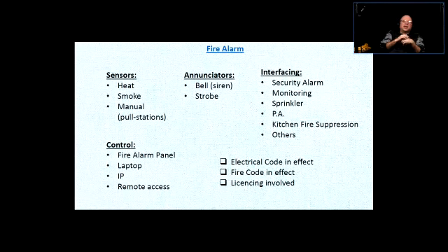So that's why in that case you would have to install something that's called a dry sprinkler system, so that there's no water, but in case there's a trigger, then the triggering of that specific sprinkler head would trigger the water being released from the main panel, right? So that's a different distribution between dry and wet sprinkler systems.